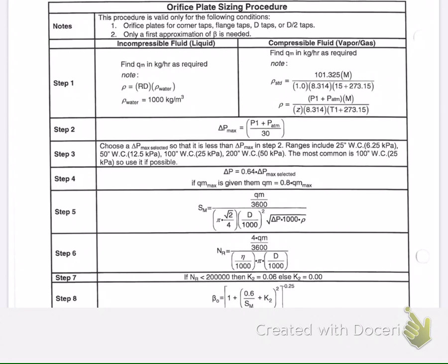We should see some of the values here, like initially when we're estimating the differential pressure that we're going to be using and the flow rate that we're going to be using. We're taking 80%, 64% with the differential pressure. So this stuff up here, we use this in valve sizing as well for dealing with a gas or liquid. So we can make sure we find our mass flow. We're going to start with mass flow.